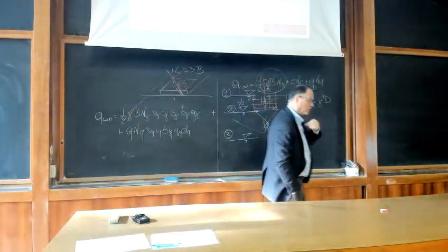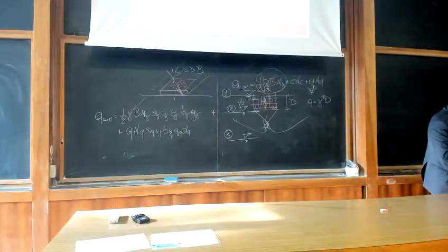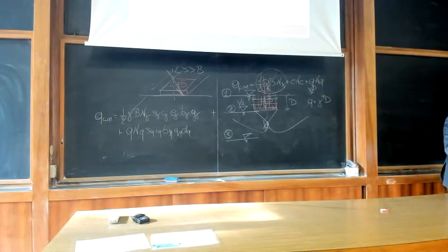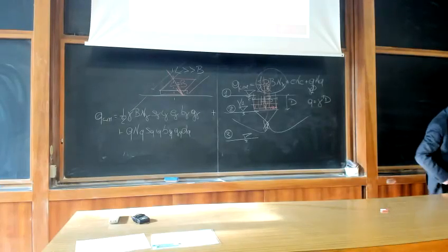And I will show in a while, as a final contribution for today, a possible and more intuitive approach to general loading instead of these factors. These are the expressions, for example, for inclined foundation factors, sloping ground factors, and what about if the load is eccentric?